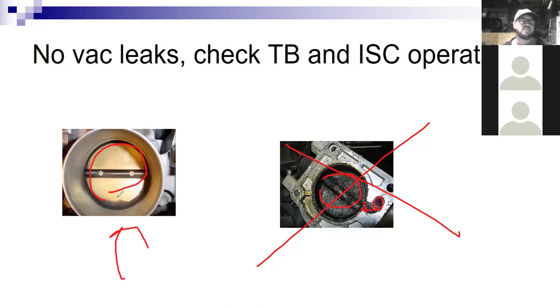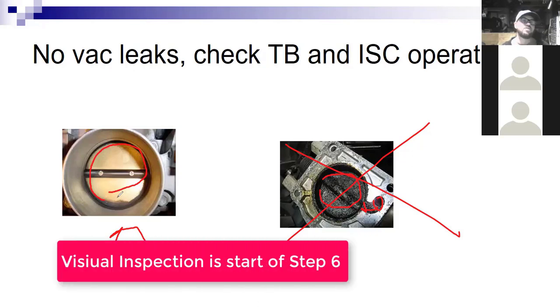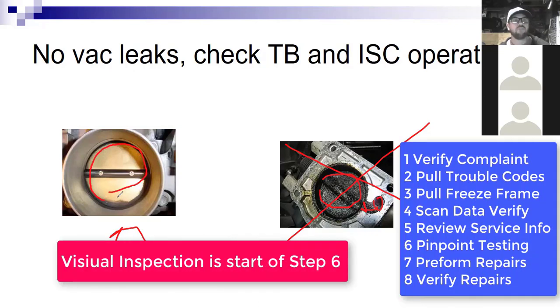So there's no substitute for a good physical inspection of the vehicle, that good thorough visual inspection. You can diagnose a lot of stuff that way, especially if you couple that visual inspection with your scan tool.